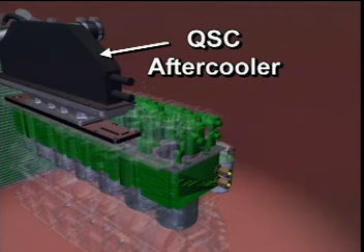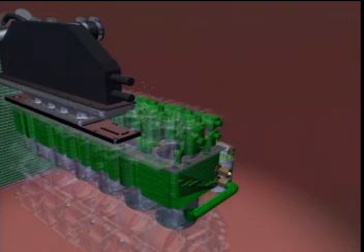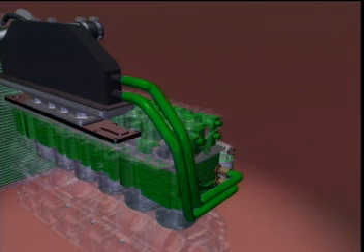Some industrial versions of these engines utilize a water jacket aftercooler installed on the engine. This aftercooler receives its coolant supply through an external line plumbed to an opening in the lower water manifold cavity at the rear of the block. Coolant flows from the aftercooler to the upper water manifold cavity at the rear of the block.